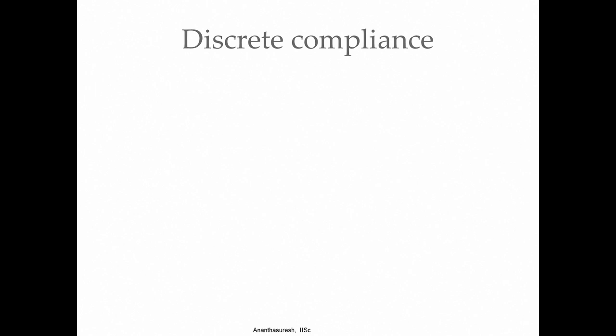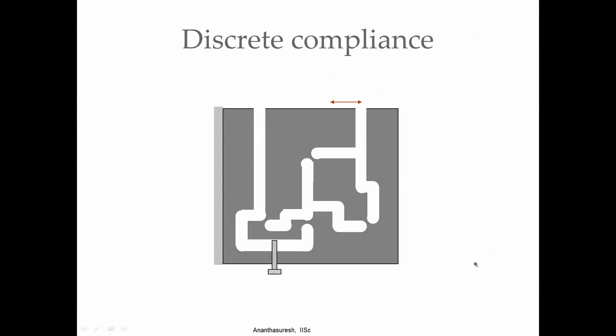So, here once again the discrete compliance, if you want, here is how you can get. You can take a sheet and mill out a slot such as this. You can take, let us say, a polypropylene sheet, which by the way is a very good material for making compliant mechanism prototypes. It is just planar machining in milling, you cut these out. What you get are the flexural joints. That is a discrete compliance. Compliance is here and here and here and here.